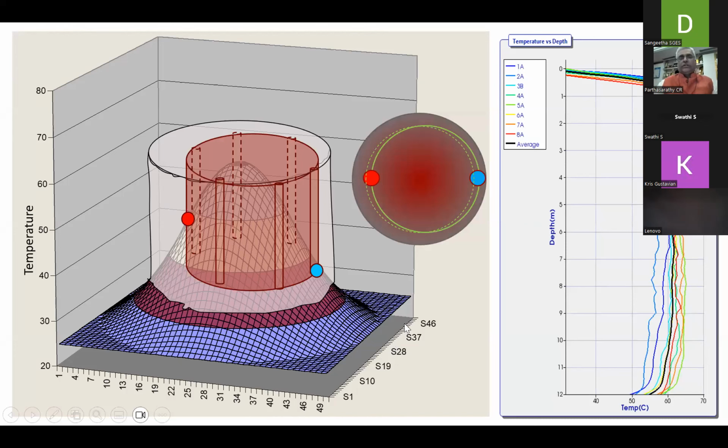And now you see a shift or a tilt in the alignment also gives you the opposite wires having cooler and warmer temperatures, while the black one is an average. If there is no alignment issue on the cage or cover issues, all of these wires' temperature measurements should have collapsed and you should get an average black one alone.